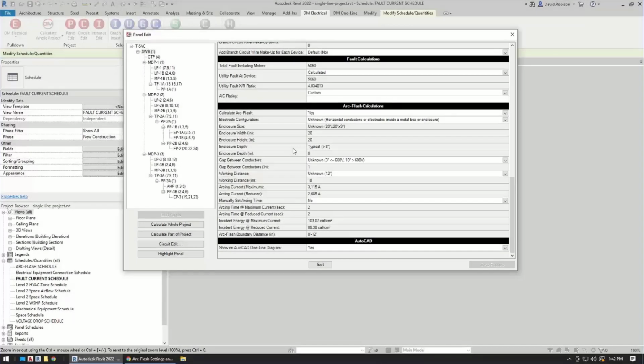To really do this arc flash, you need to take a look at what they did in the IEEE standard. The model is for 208 volts to 15 kilovolts, so below 208, the model doesn't work. It's also for 3-phase, line to line. That's what they did for their tests. They didn't actually run tests for single phase.